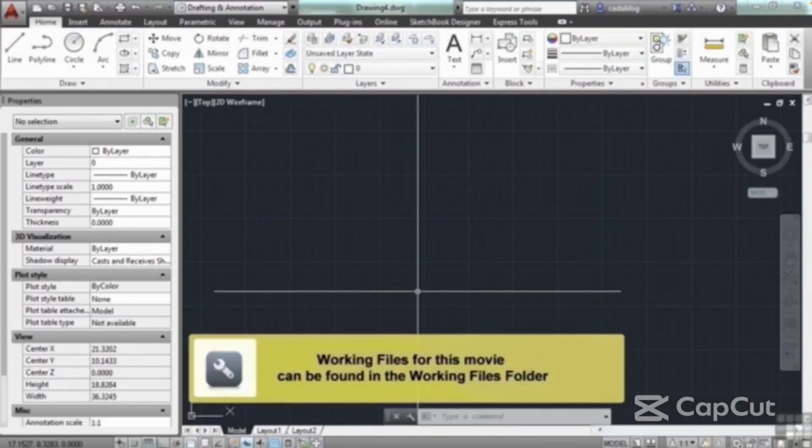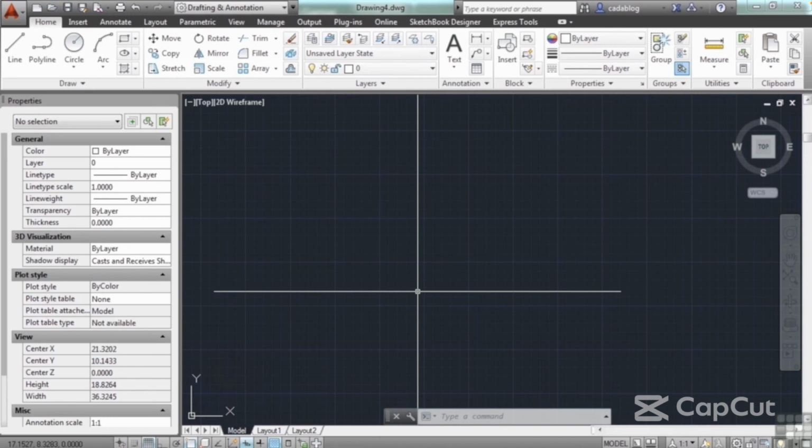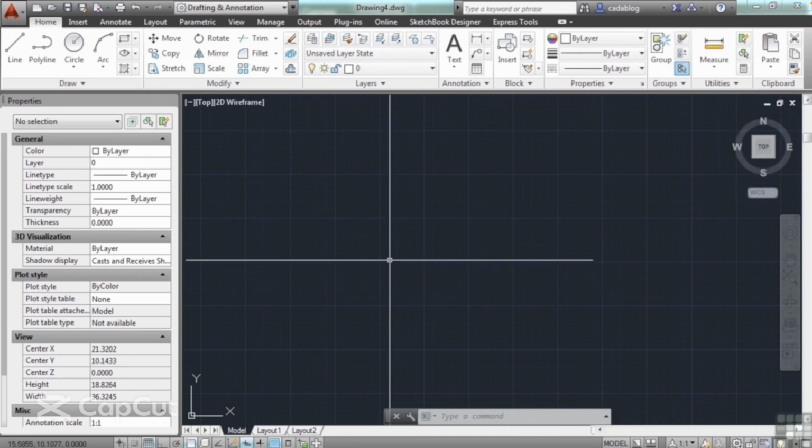Blocks are great tools that enable us to recreate similar line work rapidly. They can also contain metadata in what are called attributed blocks. A block attribute is a label or tag that essentially attaches data to your line work. Some examples of this data could be a part number, price for that part, specific comments, names, cost, manufacturer, anything you can dream of. When a block is created, you can add text to it, but that doesn't make it an attribute. You have to add attributed text to the block.